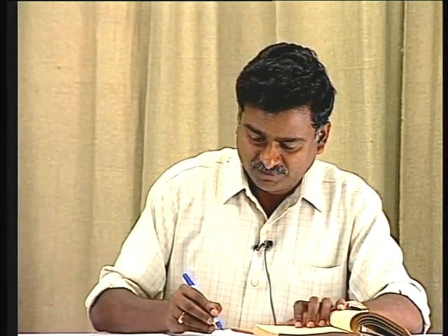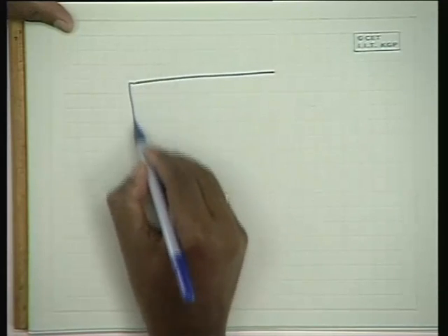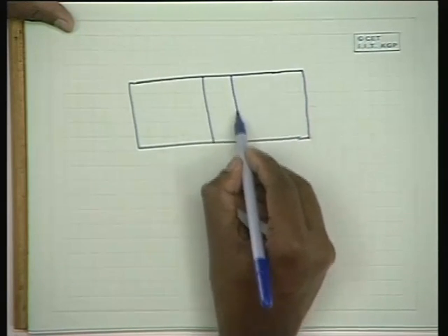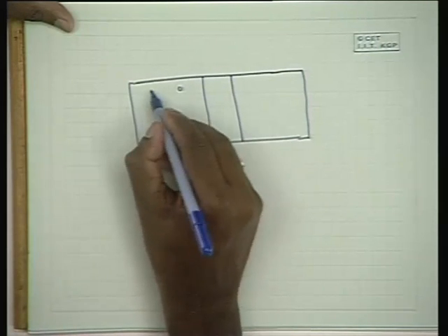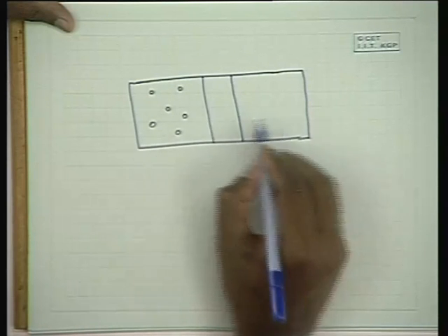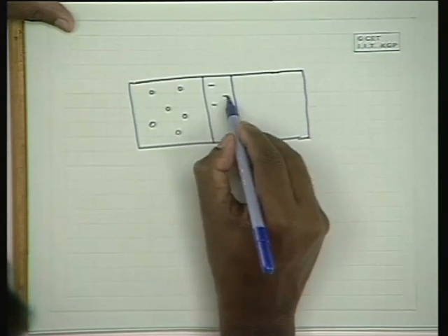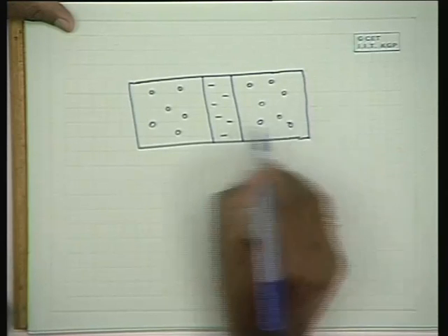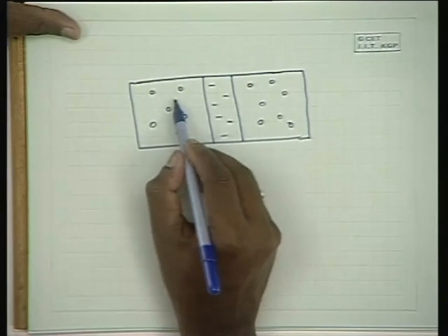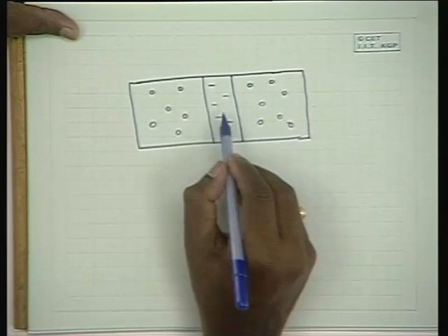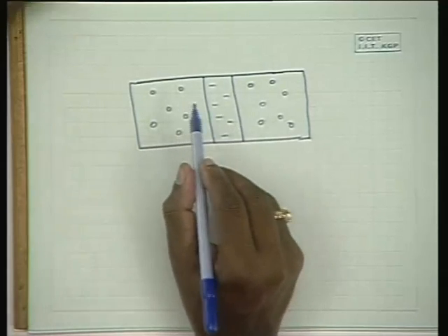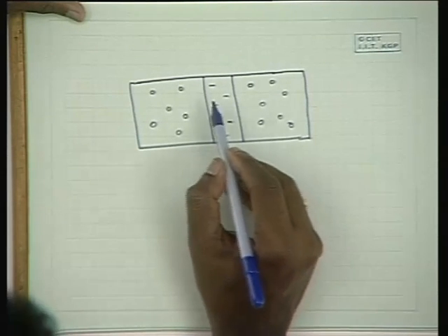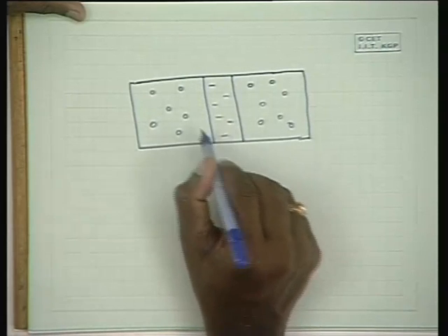Now when the transistor is formed by considering a thin base and a highly doped N side, we have holes as the majority carriers here and electrons as the majority carriers here on the base side, and similar to the p-n junction, we have a p-n junction formed the moment these two materials are brought closer with clean surface.